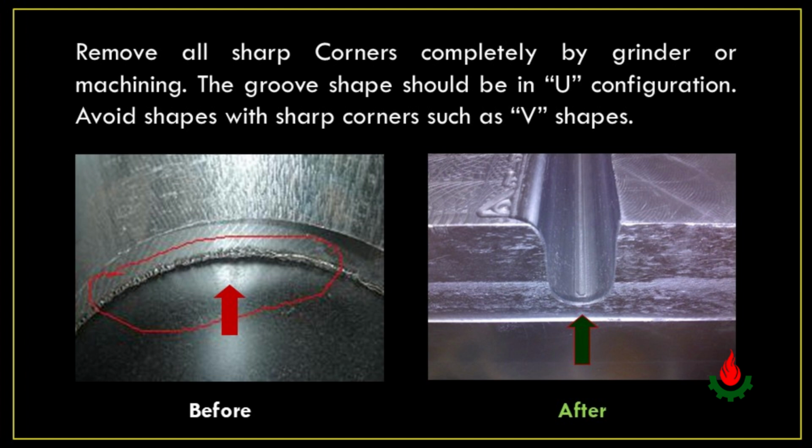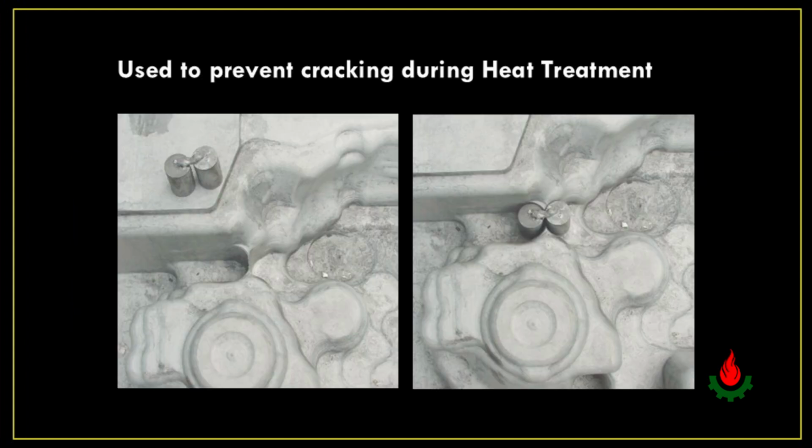The groove shape should be in U configuration. Avoid shapes with sharp corners such as V shapes. Used to prevent cracking during heat treatment.